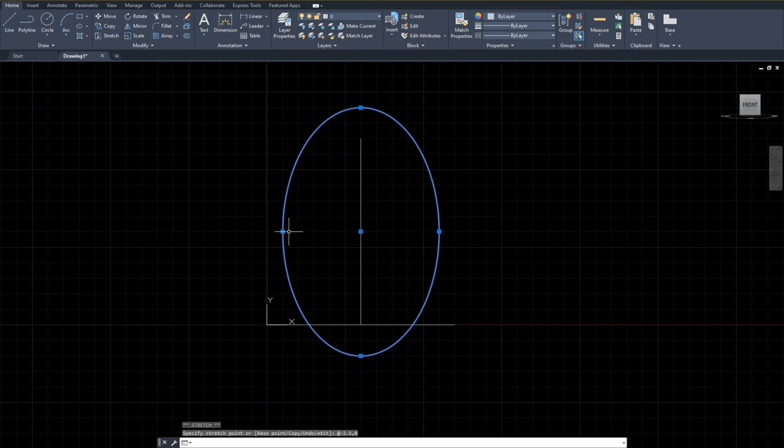I didn't want it to be too tough. Next, if you hit the escape key, the control points go away. If you select it, control points are going to show up. At this point, this is going to be an ellipse of 7 inches by 2.5. The other radius is going to be 5 inches, so it's going to be 7 by 5.